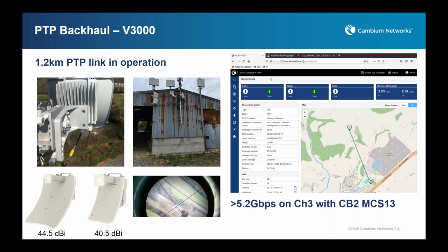Now in that rain region, we very rarely see this link drop. When I say very rarely, it has dropped once, and that's when we had something like 200 millimeters of rain in an hour. Obviously we didn't have that much in an hour, but we did have a sustained period over a few minutes, which was an enormous amount of rain. Now we've got something coming up to help out when you get that freak rainstorm. But I just wanted to leave this in your mind: this technology is not only about distributed networks, but also high throughput point-to-point links as well.